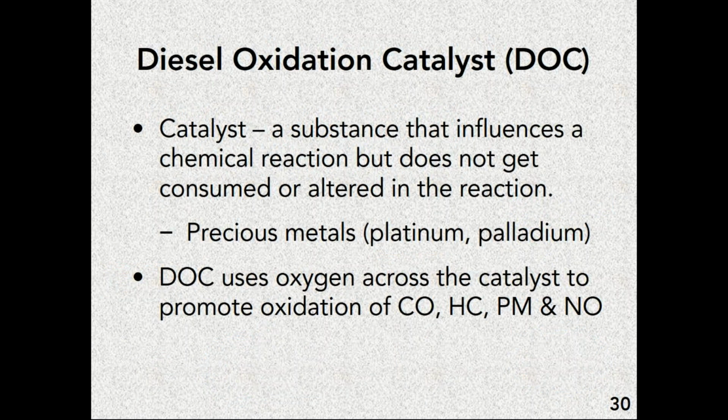All right, so the diesel oxidation catalyst, just a little bit more of an explanation. It is a level 1 diesel particulate filter, uses precious metals, typically platinum, palladium, rhodium, and it uses oxygen and NO2 to promote the oxidation of a variety of substances coming from the engine.